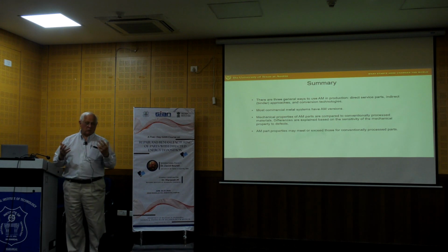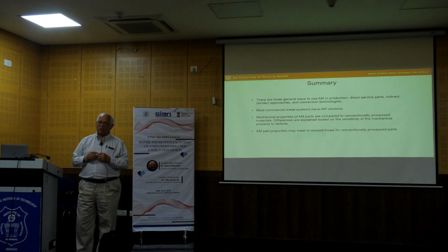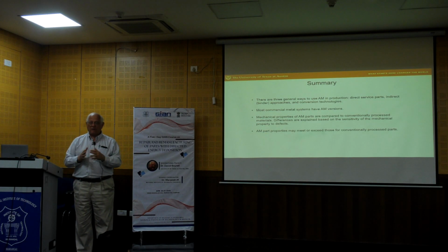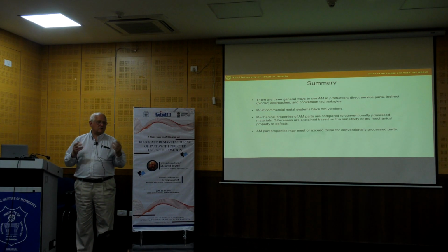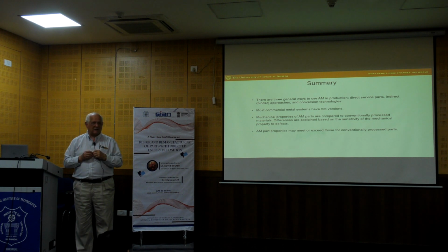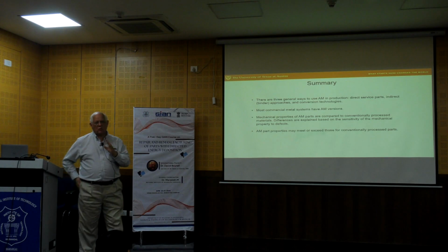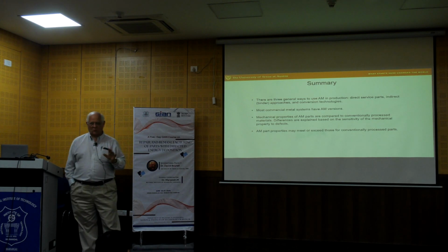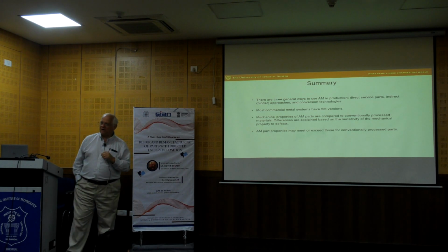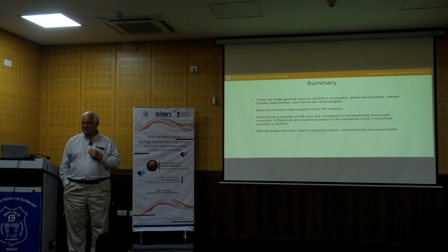Obviously for metals, that parameter would vary depending on the process, but that's the same thing with, say, weldability. Weldability varies across processes too, so there's nothing new there. But at any rate, the one broad general rule for additive manufacturing of metals using direct processes is if it can weld well, it probably can be additive manufactured well.